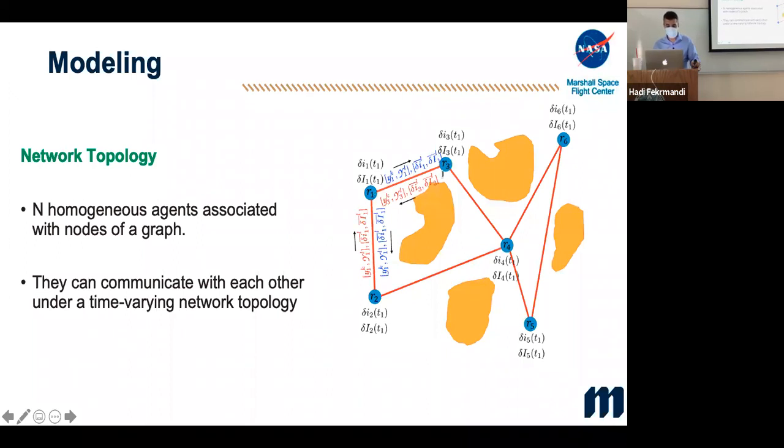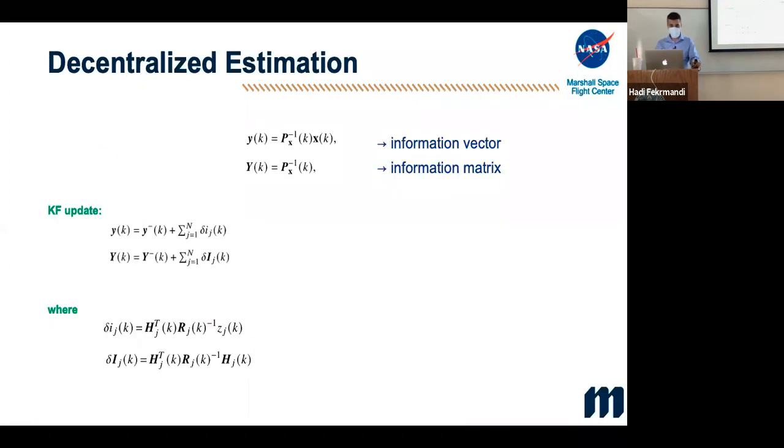That means that if I am any agent, depending on how many connections I have to my neighbors, each of them is going to give me something. Okay, this is your state. And then I'm looking at the other side, there's another state coming from there. So how do I make this consensus over multiple measurements, and also some prediction based on my own model of the transition, which was the robot unicycle model? The distributed state estimation does that by using an information vector and information matrix.